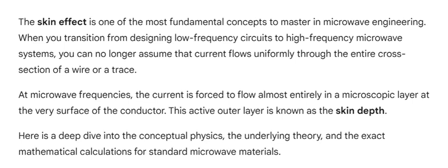The skin effect is one of the most fundamental concepts to master in microwave engineering. When you transition from designing low-frequency circuits to high-frequency microwave systems, you can no longer assume that current flows uniformly through the entire cross-section of a wire or a trace. At microwave frequencies, the current is forced to flow almost entirely in a microscopic layer at the very surface of the conductor. This active outer layer is known as the skin depth.